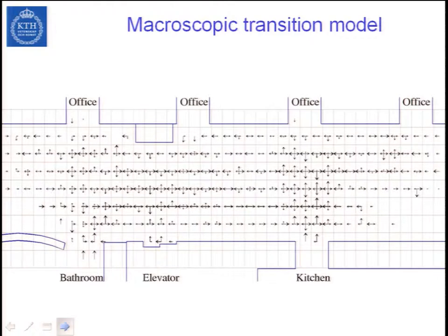Learning from 10 hours of laser scans, we achieved this overall transition model for the corridor environment. The length of arrows represents the transition tendencies from one cell to its neighbor cell. This reflects how people move in this corridor, and knowledge of this enables inferring future trajectories.